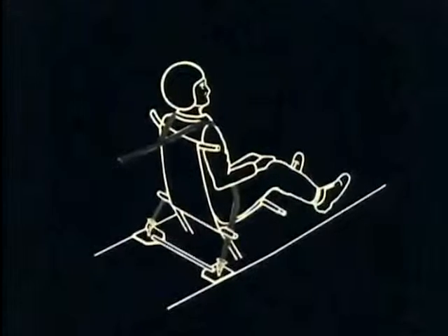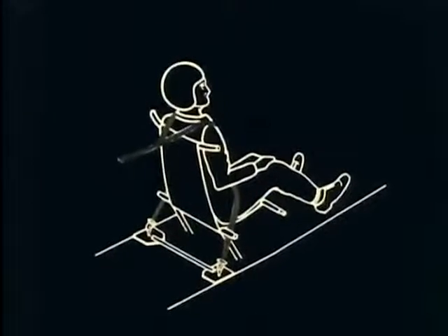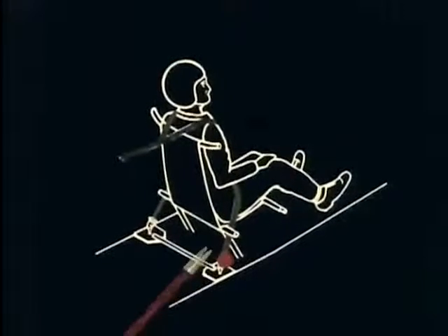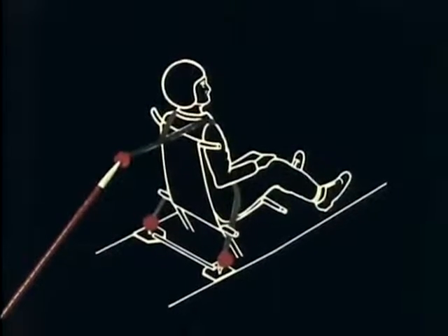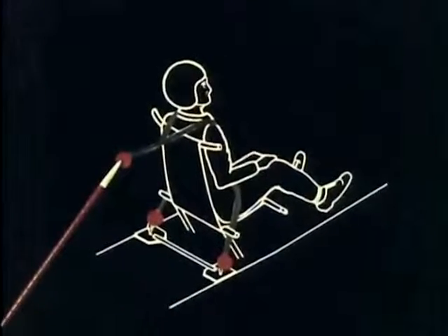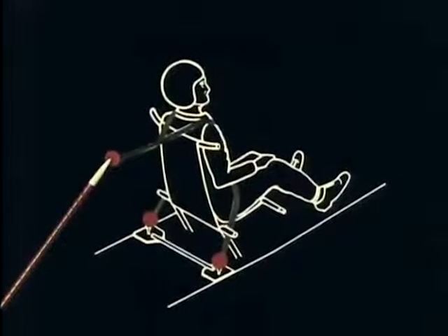If the restraining harness is to serve its purpose, it must not break. In order to tell the designer how strong to make this harness, the forces in these straps were measured in the crashes. To obtain this information, tensiometers were located at each end of the seat belt and on the common juncture of the shoulder harness. The sum of the forces on each end of the seat belt and the force measured in the shoulder harness in the 60-mile-per-hour crash for the dummy in the rear seat are plotted against time after the